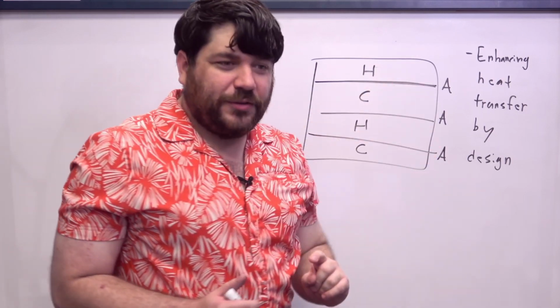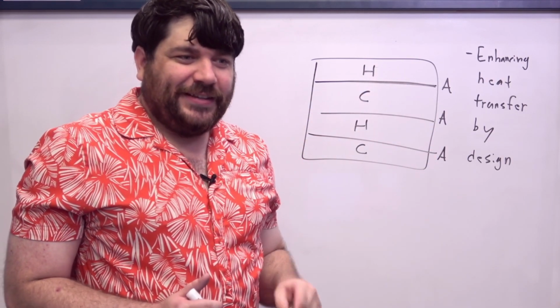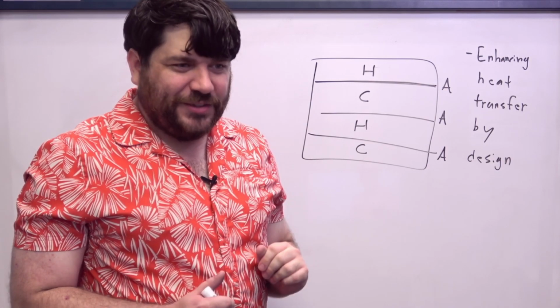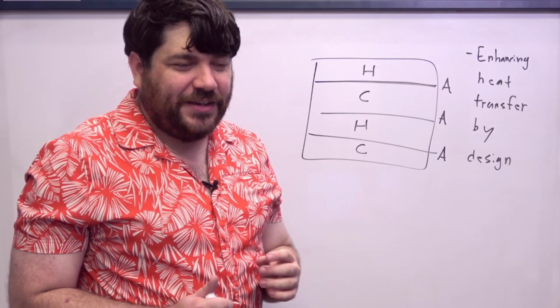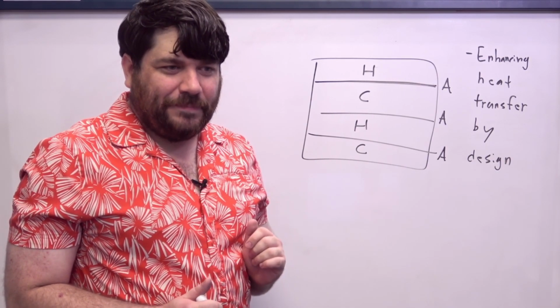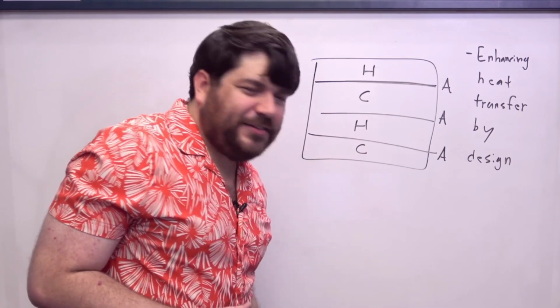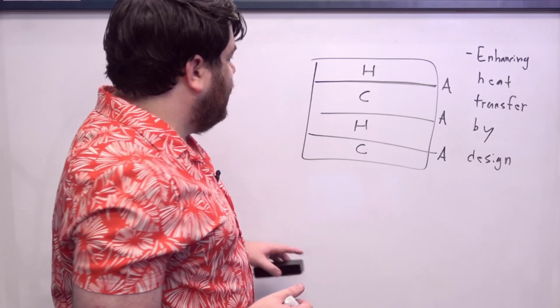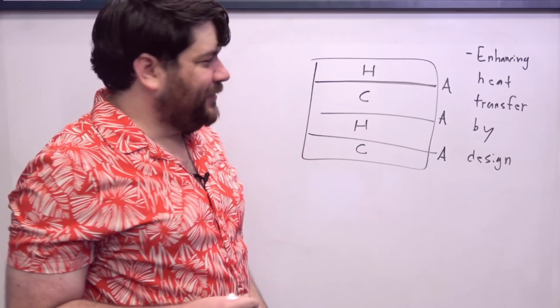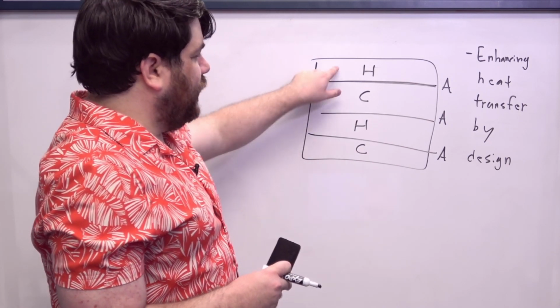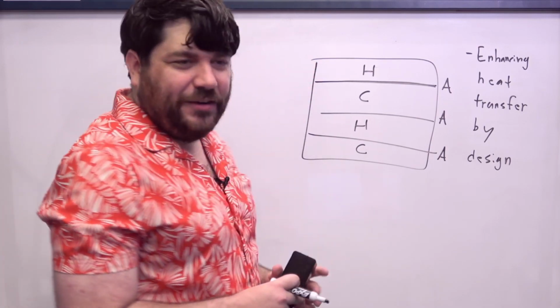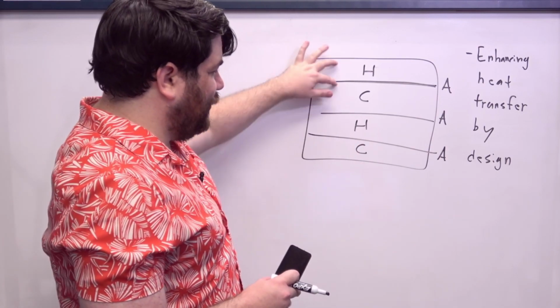And because we've tripled the surface area, that seems to suggest that we've cut the thermal resistance down by 3 and then enhanced the heat transfer by a factor of 3. And sure, this works, but why stop here? If I could take one group of a hot-cold chamber and do this kind of split, why don't I do it to these 2 as well?